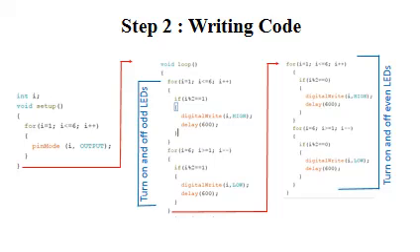Now it's time to write the logical codes in Arduino software. We need a variable for storing the pin numbers. Here I have declared a variable named I. It will get the pin numbers from the for loop. In the void setup part, the first for loop runs for the values from 1 to 6.